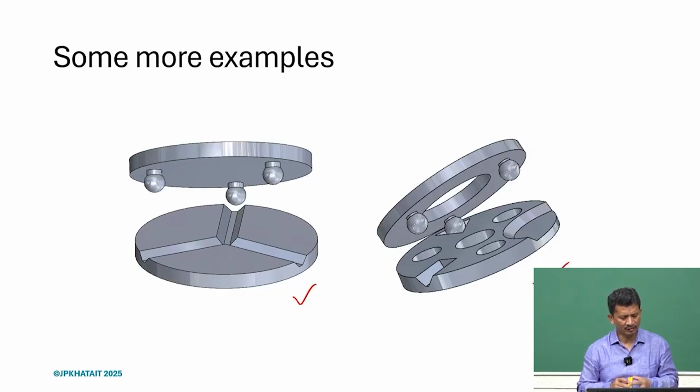What we see here is there are grooves. I have one here, and maybe we'll show it in detail in videos later. Here we have the grooves and a spherical ball joint, and they come in contact, and because of the design itself, the location is defined. I can put them together and it will go precisely to the same location even without looking at it. So, this is by design.